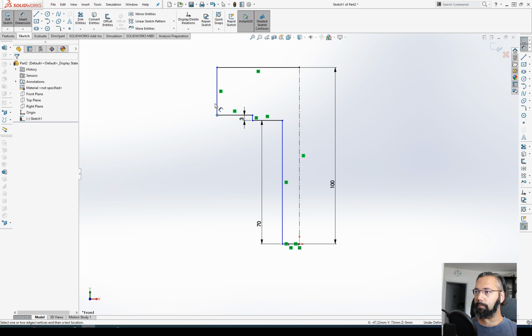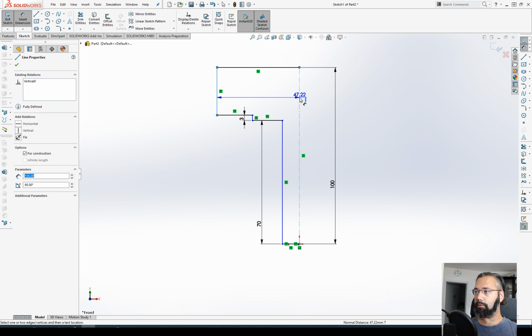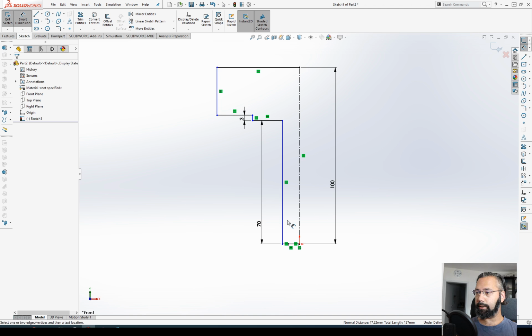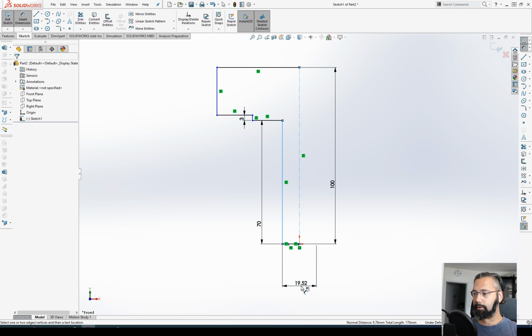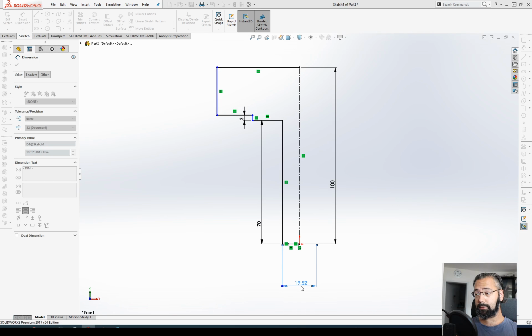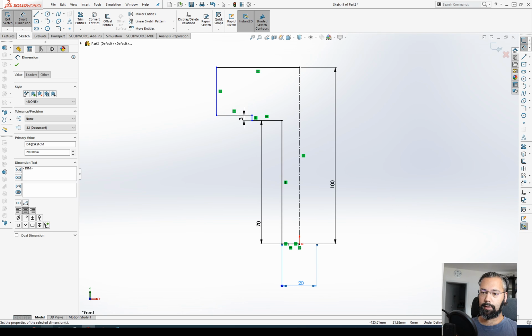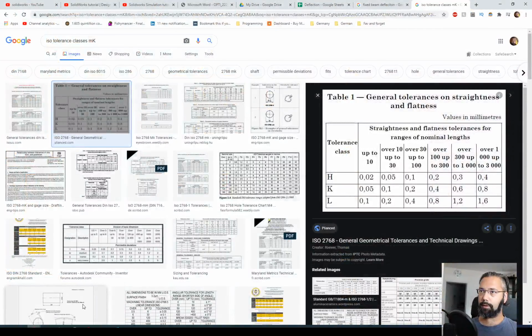Yeah, all right, cool. Now since this is a revolved part, it has diameters, and when you want to create a diameter, you can do either half, or when you click, like let's say I want to decide on this diameter, and this is now the radius, and if you go over the center line, it becomes a diameter. Amazing. Actually, let me check something.